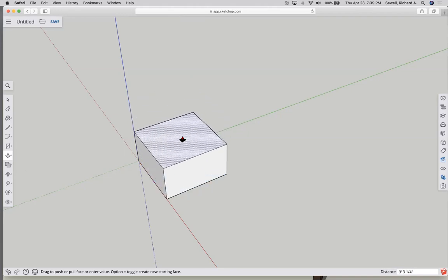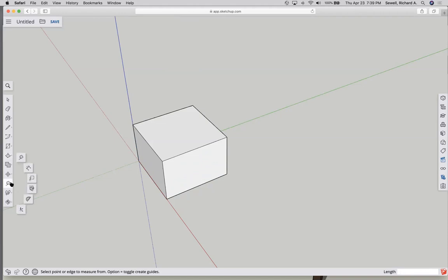And again, as I pull this thing up, you'll see my distance in the distance measurement pane changing. And I can do the same thing. I can say, well, I want that to be 4 foot tall. There you go. It's 4 foot tall. Okay. Now I can check that with my measurement. See the little measurement tool down here? There's a little tape measure. There you go. I can check that and see the measurement says 4 foot. So I know that's 4 foot.